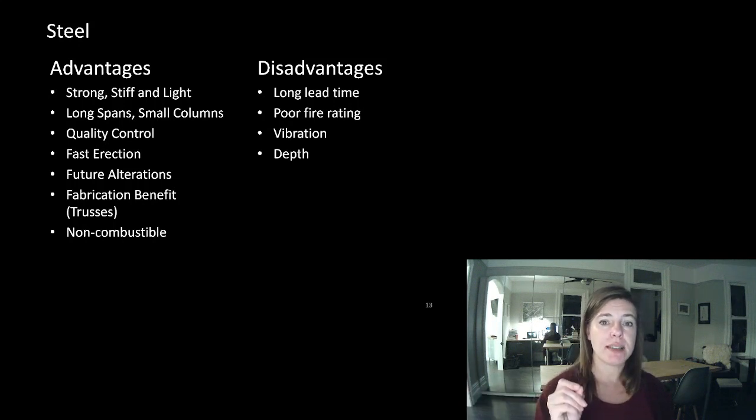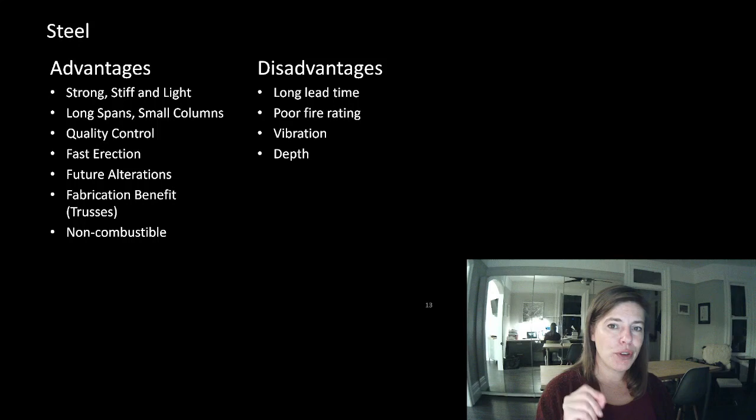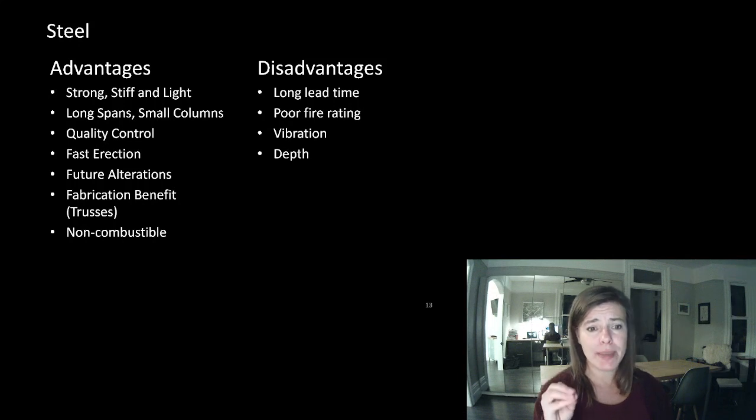Except for HSS steel, there are specific guidelines that it can't be too strong either. And you're thinking, why would too strong be a problem? We would always want it to be stronger than it could be. That's true unless we're talking about capacity design. And capacity design is this part of seismic design where we absorb energy while our steel is yielding.